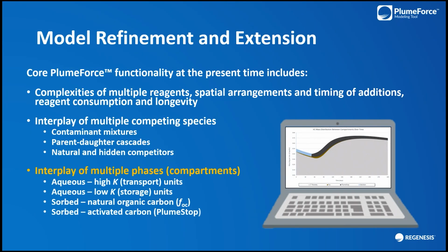PlumeForce also considers the interplay of multiple phases or compartments. It considers the aqueous phase that we principally measure in groundwater samples from monitoring wells. It looks at the aqueous phase in the lower permeability zones, zones such as the silts or clays that may harbor mass that can back diffuse out at us. And it considers the mass sorbed to the natural soil organics.